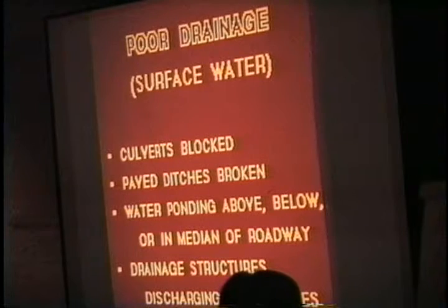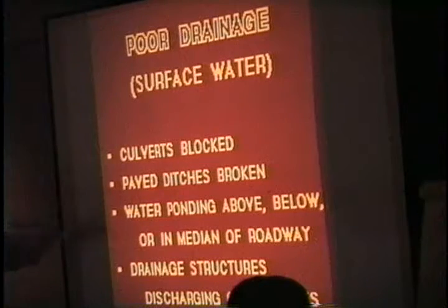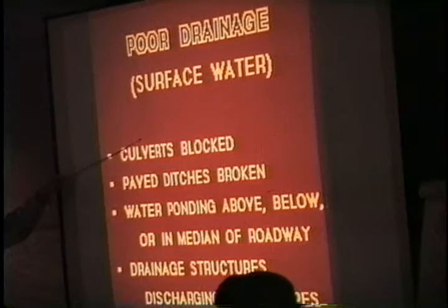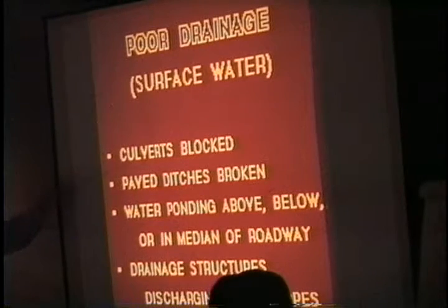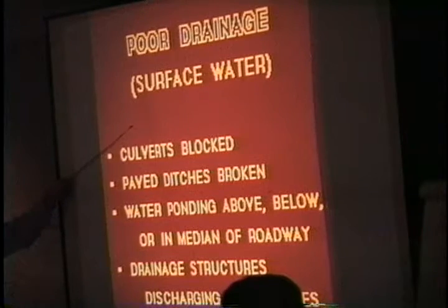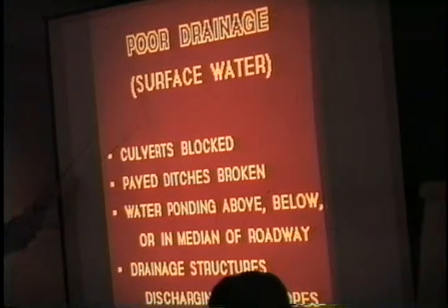People are all worried about the bump at the end of the bridge, so you get a little approach slab, but no one paid much attention to getting drainage off the bridge. Bridges are designed for water to flow sideways or longitudinally. Could be both.